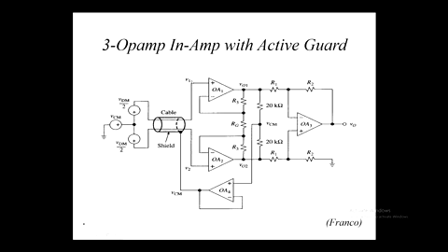If this is half of a differential voltage, and this is minus half of a differential voltage, then we've got minus half here and plus half here, so there's a definite voltage across that resistor inspiring a current flowing upwards, and so there'll be an amplified version of V1 on 2 here and minus V2 on 2 down here. Pardon? Does that depend on what RG is? Well, it will, yeah. It'll be an amplified version.